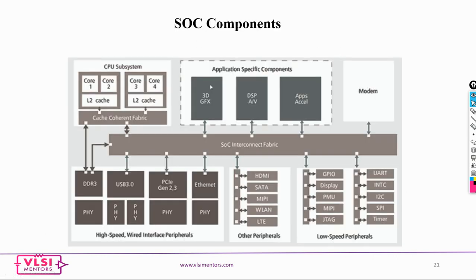Now, what is a typical SoC? When you look at your mobile chips, you have multiple CPUs, say a quad core CPU, and you have your graphics, and then your audio video DSP cores, and then your modem, say a 4G or 5G modem, and then your LPDDR memories, and then your USB support, and then you might have Wi-Fi, and then all the other peripherals, wireless, Bluetooth, and so on. Then your display unit, power management unit, and your testing, and all of that.